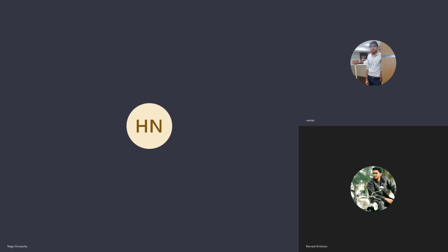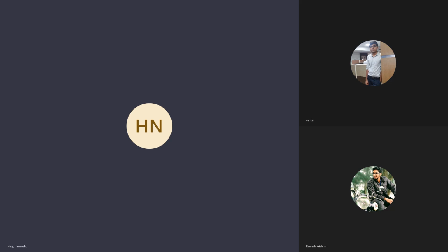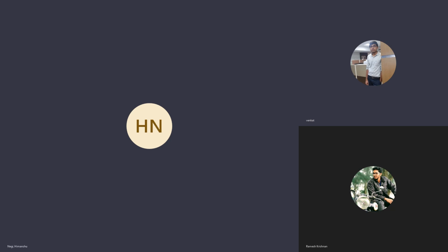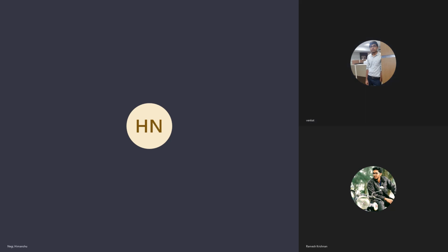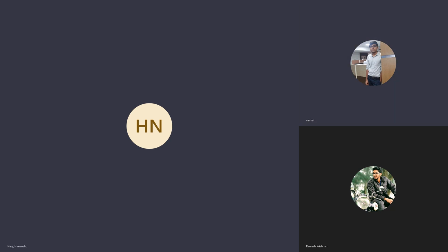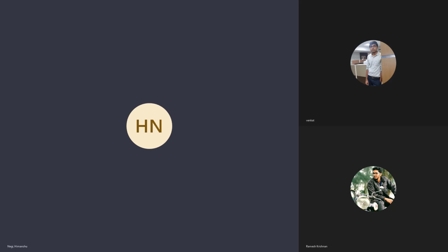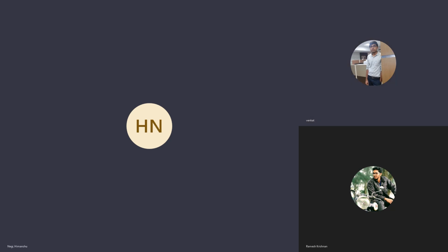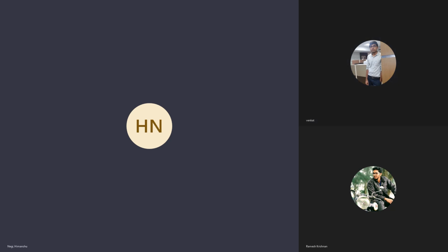But in my understanding, if the surge arrestor is bonded down, it will still damage the sheath, I think, because there will be a voltage difference between this earth and the sheath earth, this mat. So it is going to create a potential difference, and more current will flow there. Maybe if you bond them together, it will still transfer, but it won't create any stress on that cable jacket, I think.